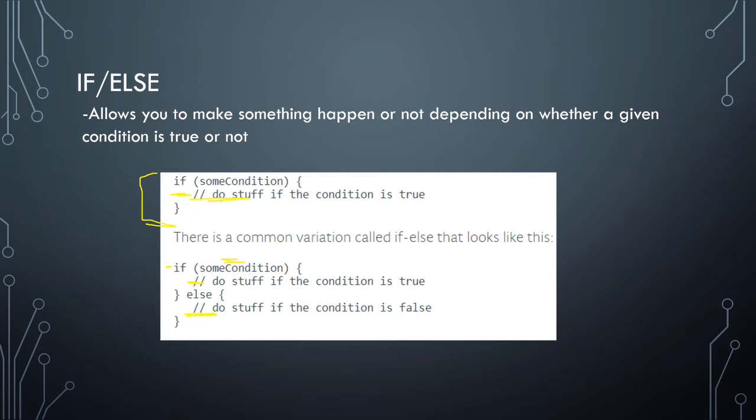So you could put it on a timer if you wanted, but you would have to work that into your if code. Another way to do this is to say down here, by using an if-else command, we can say if the push button is pressed, then turn the LED on, or else turn it off. And that's what you'll see in your lab assignment here in a few minutes.